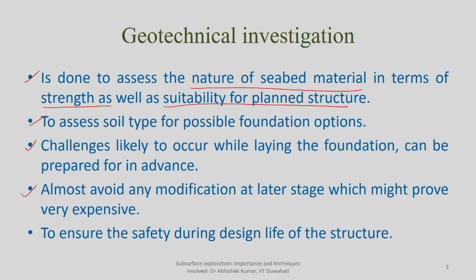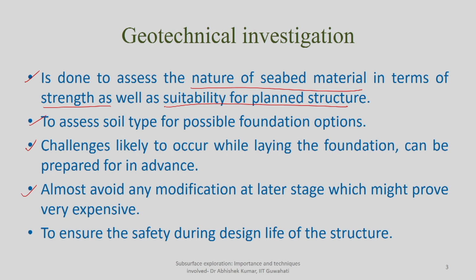So, after those challenges, you must have explored all possible types of foundation and what the challenges are if you go for those kinds of foundation, whether in terms of money involved, depth of exploration required, the type of foundation to be provided, or the infrastructure or machinery required for laying any kind of foundation, and the suitability or availability of those machines. So, you can avoid almost all possible modifications to be done at a later stage, because again those will prove very expensive.